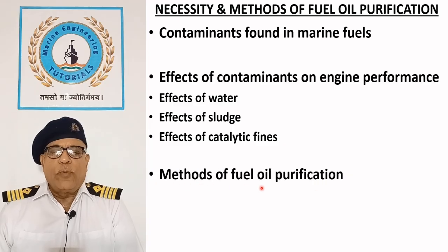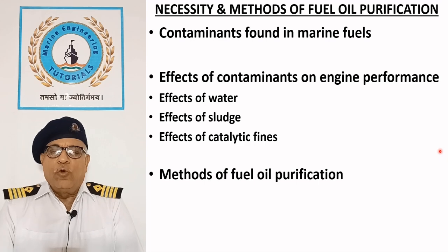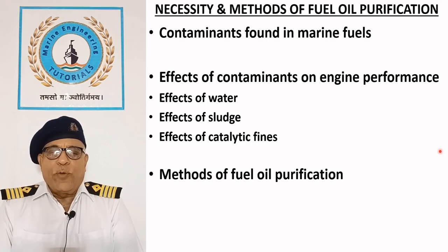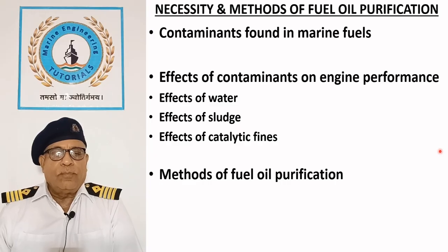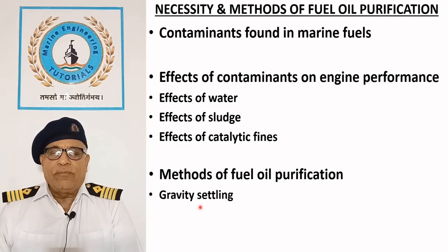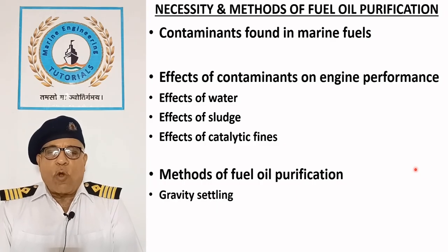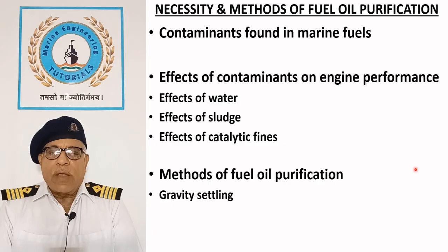Methods of fuel purification. Marine fuels are treated to remove impurities by all the following methods before the fuel enters the engine. Gravity settling. Heavier particles and water settle at the bottom by gravity due to the density difference. It forms the first stage of fuel oil purification. It is a very slow process and not effective for fine particles or emulsified water.